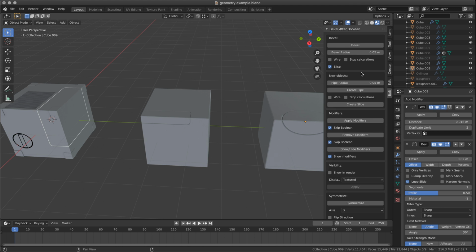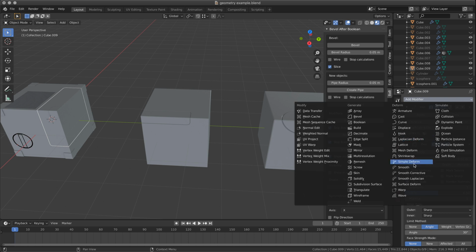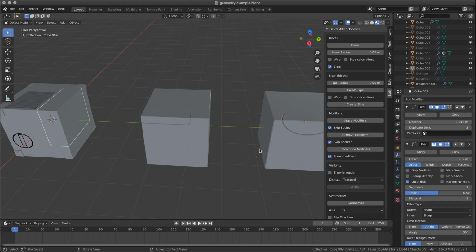So you can go back, and as long as you don't add any vertices, faces or edges, you can keep the modification, and you can go back into edit mode without destroying what you're doing. And then you can remove that edit mode, which is really like a modifier. It's like a smooth modifier, but you go in edit mode and do your tweaking of the geometry. So we're getting there. I think we will have something like this at some point.